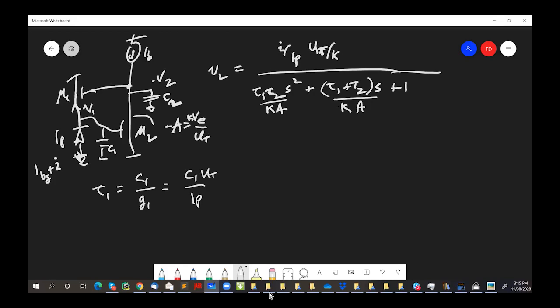And then there's an output time constant too, which is the time constant on the V2 node. And tau 2 was C2 divided by what? G out. It's the output conductance of this amplifier, G out 2, which was C2 divided by, okay, so what's the output conductance?